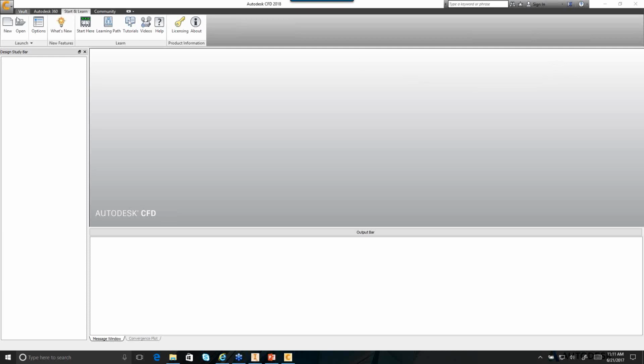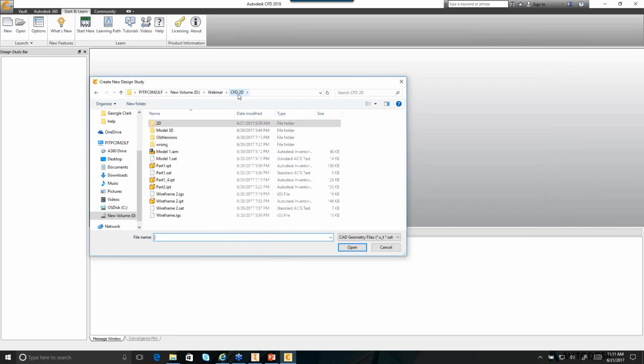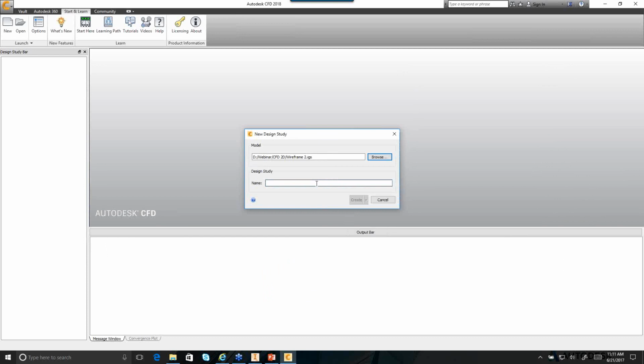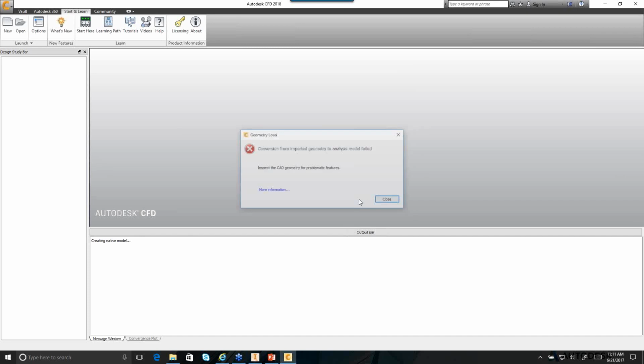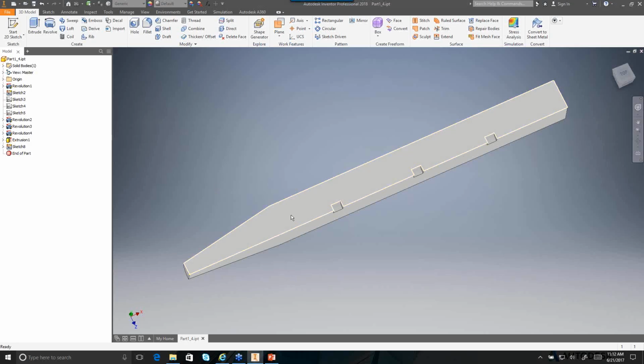Okay. Yeah. So I'm going to go to File, New, and browse here. And if we pick up just the wireframe IGES file and try to open that, give it whatever name, it will not like that, because that wireframe is just the wireframe. It is not surfaces. So what I'm trying to say here is that your 2D model, your CAD model, has to be surfaces, not just the wireframe sketch. So what you would need to do is you would need to go in and make surfaces.